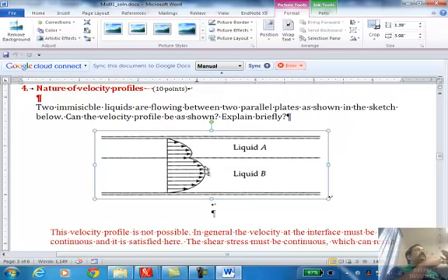When the shear stress is 0, it is as if you have a free slip condition, right? It's as if the fluid is slipping past freely. So the fluid that is between these two maxima is taking a free ride. It's as if it's being pumped without any energy requirement, without any shear acting on it, because both are shear-free surfaces. It's as if they are moving without any energy expenditure, and that's not possible either. Okay, so that we didn't discuss.